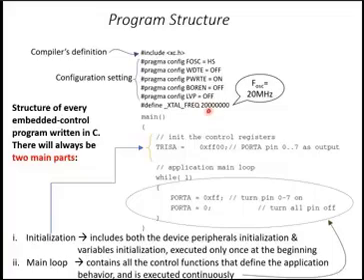And then the last one, you define the frequency of the microcontroller. In this case, our frequency of the microcontroller is 20 megahertz. How do you know? That is related to the hardware. What is the value of the crystal oscillator connected to your microcontroller? If it is 8 megahertz, you put 8 megahertz here. So everything must be the same as the actual hardware.